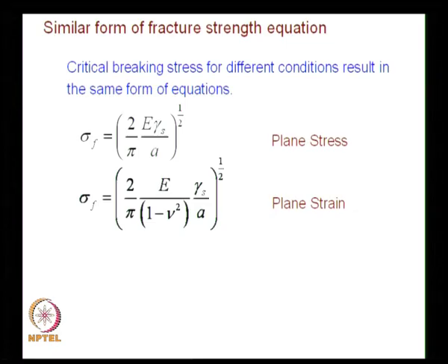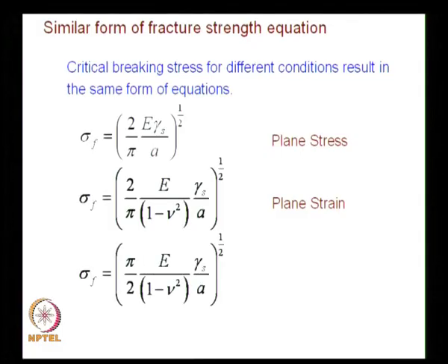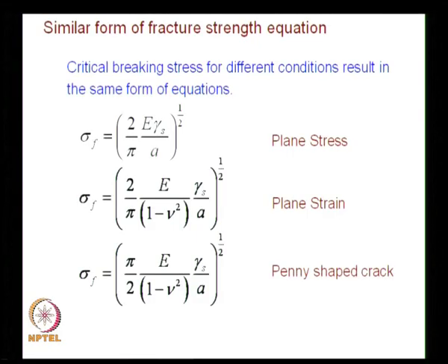And people have also looked at another problem. You know, when you have a 3-dimensional solid where you have a penny shaped crack, people found the expression only the numerical factor has changed, the form remained same. You have Young's modulus, you have surface energy divided by crack length, that remained same, only the numerical factor was changing. And this is a very important observation utilized by Irwin to generalize crack problems.